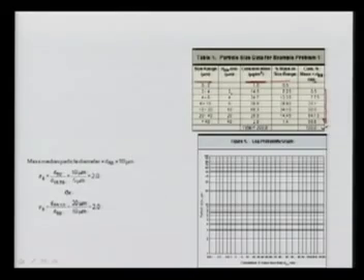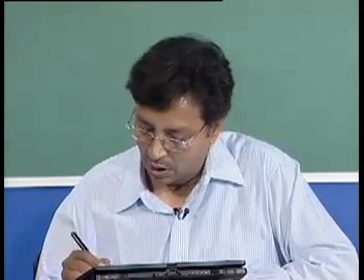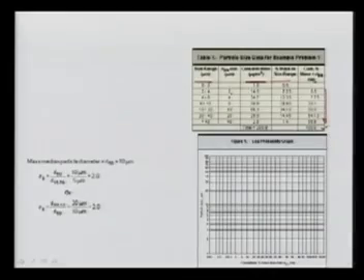Then we have to plot the whole thing on the log probability plot, because you want to find out if the distribution of the particle size is log normally distributed. So what we have done here on this side, we have plotted dPA, the particle size, or this column.